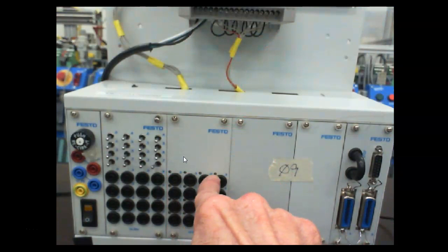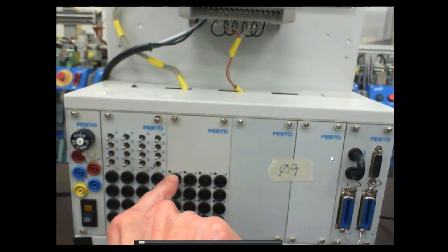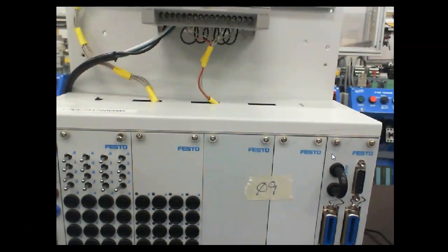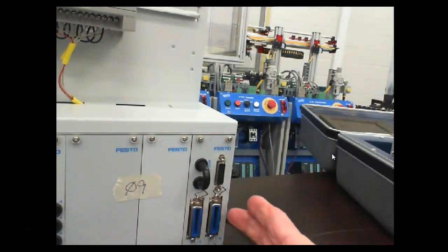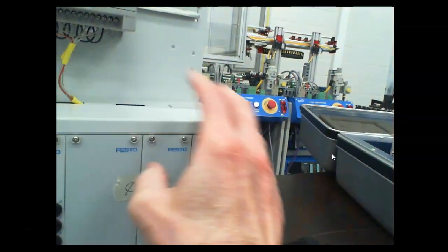Each output has an LED on it that indicates when the output is true. So we're not going to hook up a motor. I might hook up one and show you how this would work. But we'll say, okay, I want to turn on motor 1 after 5 seconds. What would happen is an LED would come on, and this guy right here would go to 24 volts because it's outputted from the PLC. So we could hook up a 24-volt motor to this, or a relay. So this is the trainer that we'll actually be using. We're not going to use this one this semester. This section over here allows us to connect whatever PLC up here.